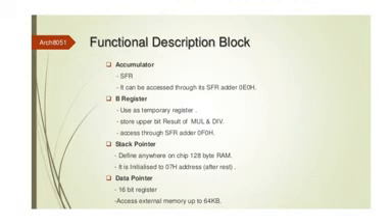This stack can store data as well as addresses during execution of a program, and it is initialized at location 07H. Whenever I reset, it will directly point towards the 07H location in the internal RAM.